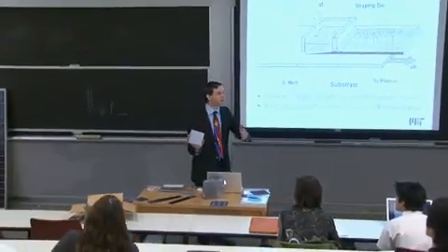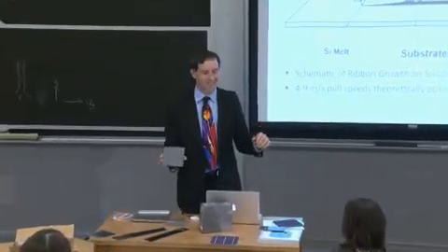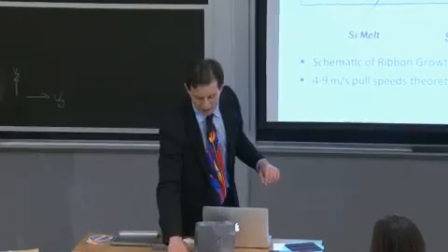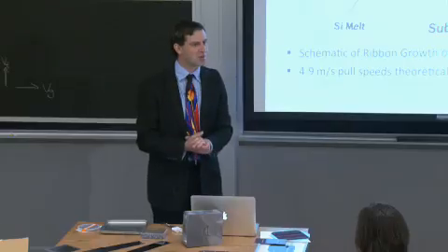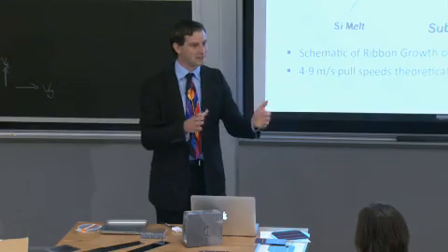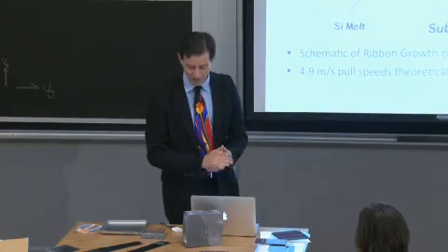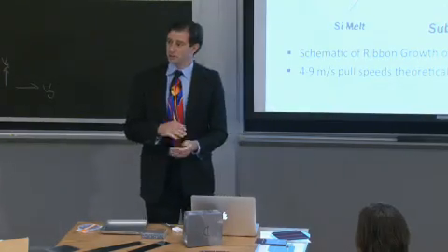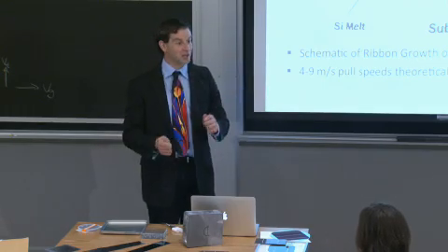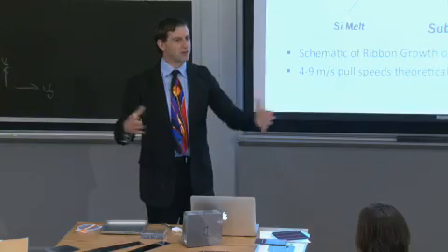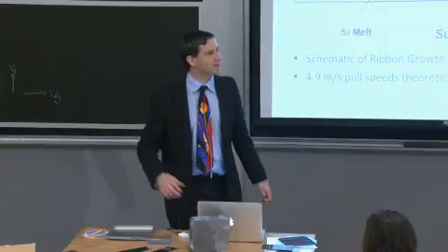Most laboratory devices that you and your colleagues will manufacture are on the order of 1 by 1 centimeter or smaller because of a variety of factors. One is the transparent conducting oxide, as we solved in our homework problem. We're limited in how big we can make the device by the sheet resistance of that transparent conducting oxide. Another problem that we typically run into is just that we're not able to deposit uniformly over a large area. We don't have the deposition equipment for it in our labs. We're trying to optimize a new material, and we don't necessarily worry about making module-sized devices out of it.